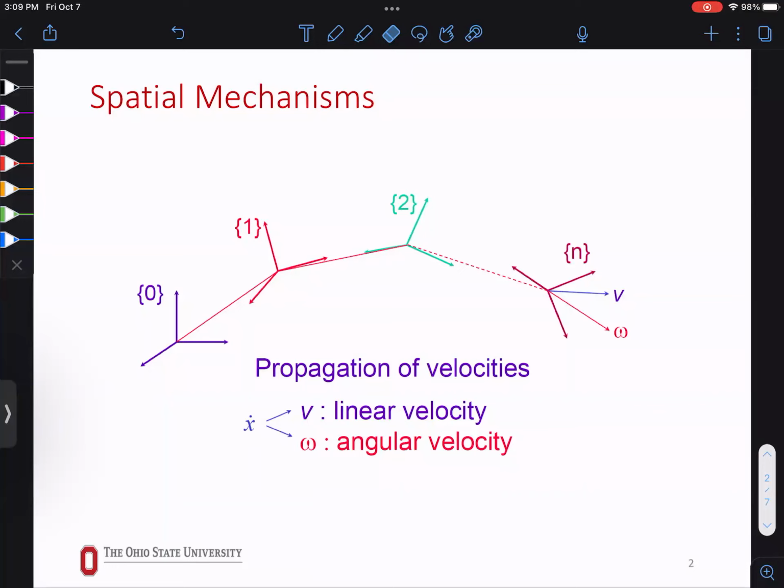So this would go fast, like 2 meters per second or whatever, but it depends on what the velocity of this one is. It would have an impact, right? So the velocity propagates through the joints. We're going to find each velocity and consider them all together. We're going to simplify the problem: let's walk joint by joint and then put this together to create that mapping, because the mapping is the same thing, right? How each of those impacts the velocity of the end effector.